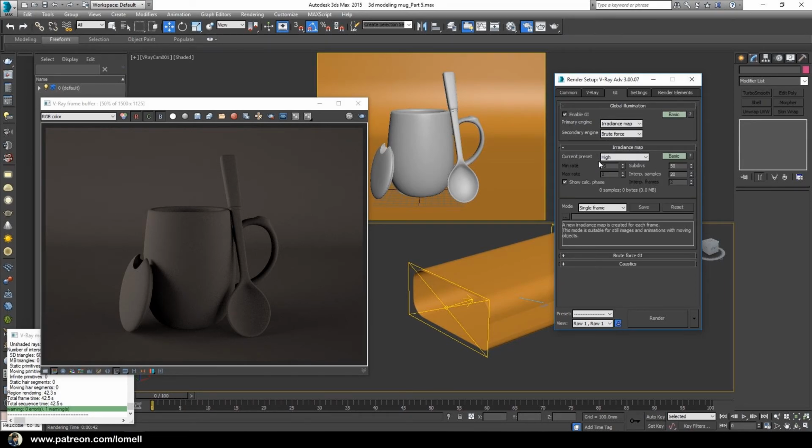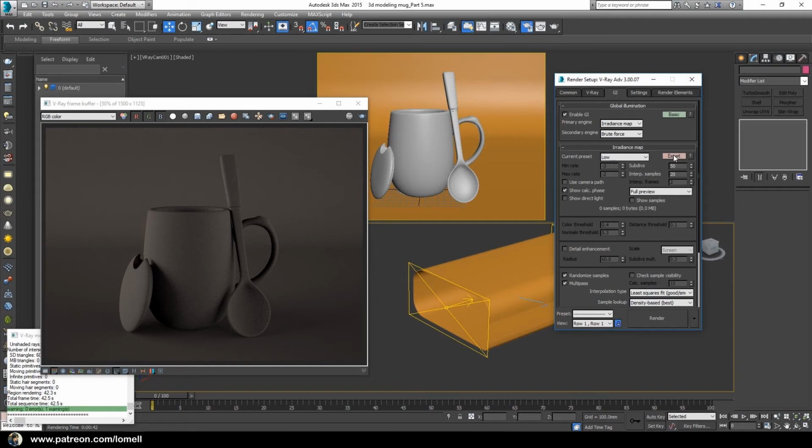And you can see here now that it uses high settings. So let's change it. Click this drop down arrow and let's change it to low. Okay, and now let's change this basic into expert mode so that we can access this multipass and uncheck that, because leaving that multipass checked, the rendering will calculate the light cache and global illumination cache multiple times.